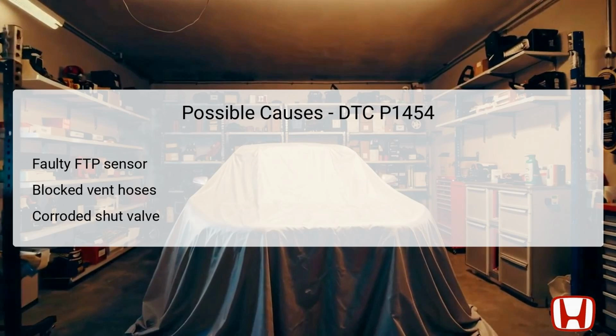Each potential failure point must be investigated, as fixing one may not resolve the underlying issue if others are also impaired. Always ensure to check connections to rule out loose terminals that may lead to intermittent failures.